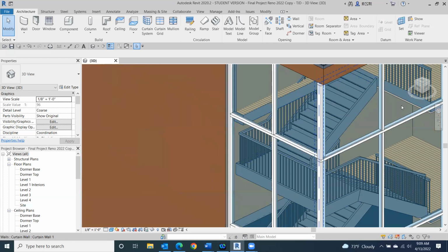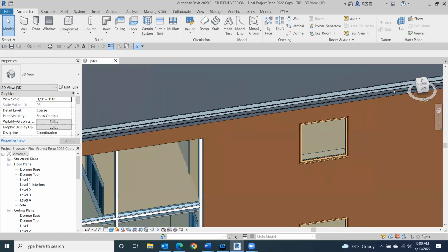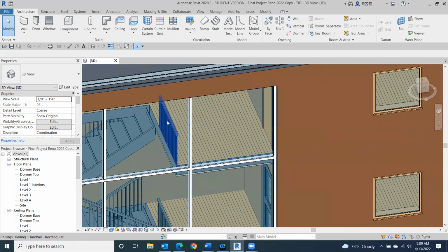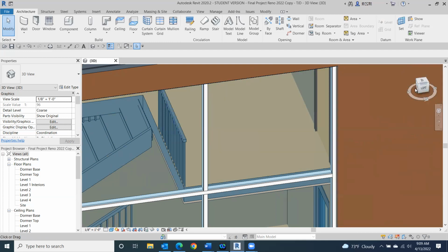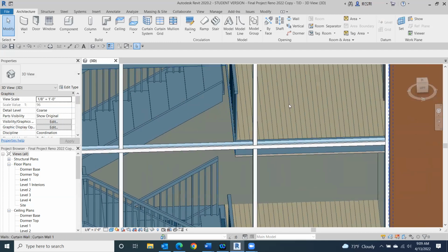It's still intersecting the stairway, especially the stair railing. If we take that side view, you can see that the stairs aren't quite reaching the floor. So there's definitely a gap there. Easy to fix. Go back to a straight top-down view and re-edit that floor.